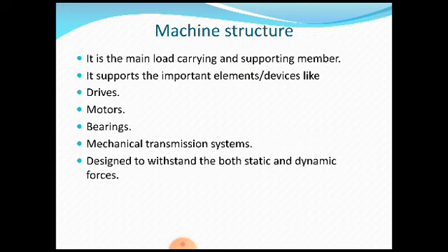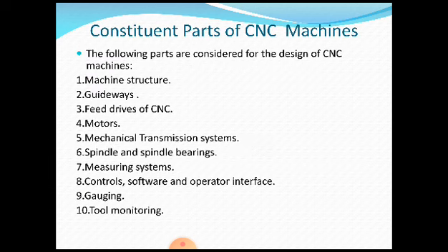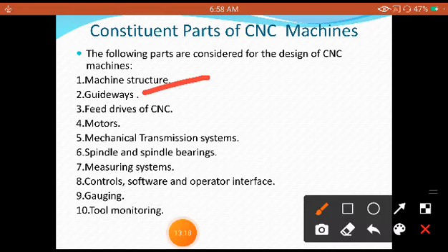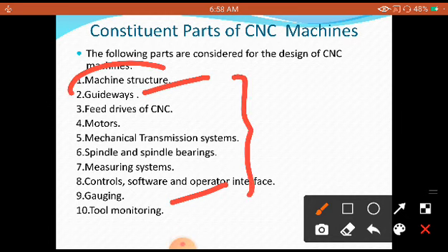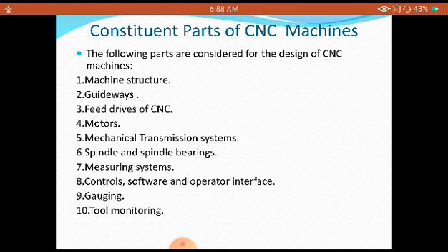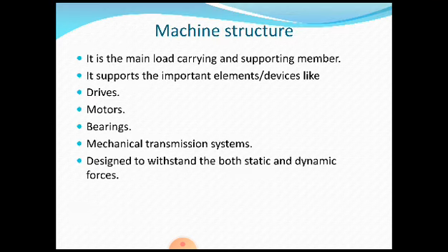So what is its function? Whatever devices I have mentioned here, starting from the guideways to the tool monitoring system, all these elements are supported with the help of the machine structure itself. That is what needs to be understood by you. It is the main load carrying and supporting member. It supports the important elements and devices like drives, motors, bearings, mechanical transmission systems, designed to withstand both static and dynamic forces.